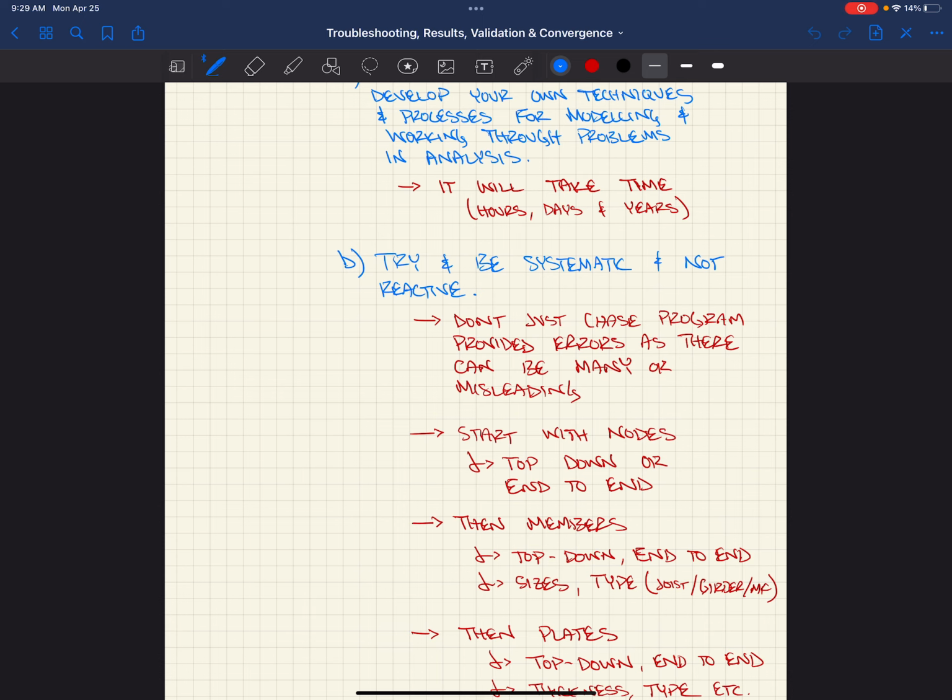So the find tool is really helpful in this regard, because it's separating all of your member elements and it gives you all of the materials. You can sort all of your members by the material, and then you can select those members, and it's going to highlight all those members in your model. So if you wanted all of the members at a given cut to be that material, you could sort by A992, select all the members, and then select the cut you want. You could step through top to bottom of your building and make sure that at each cut all of the members are highlighted. You would know they're all A992.